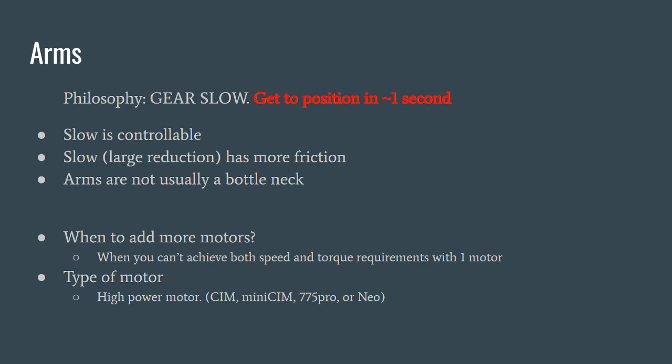The open motors have a fan, like a plastic blade, that when it spins, it moves air around, and it cools the motor. So you'll see on the Versaplanetaries and stuff, there's actually like a little gap between 775 Pros and the front of the motor because it wants to leave space for air to be able to go in the front of the motor so that the fan can draw air through the motor. Right? So it's very important that for open motors, you allow air to come in where it needs to come in and leave where it needs to leave because it needs to cool itself.